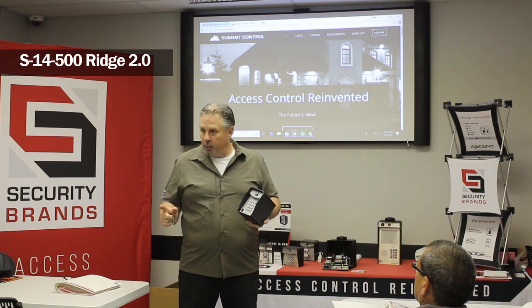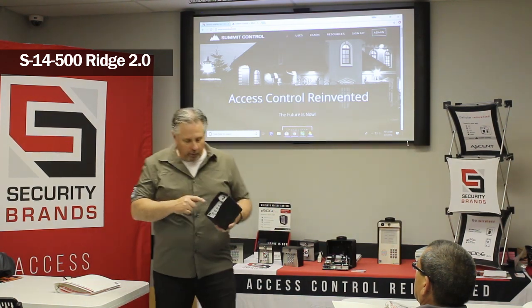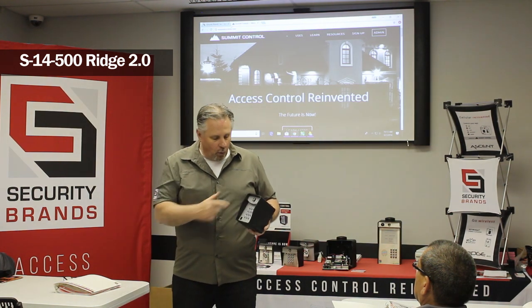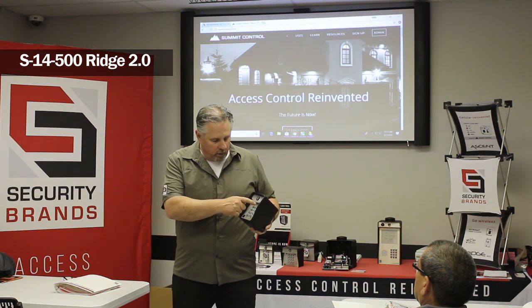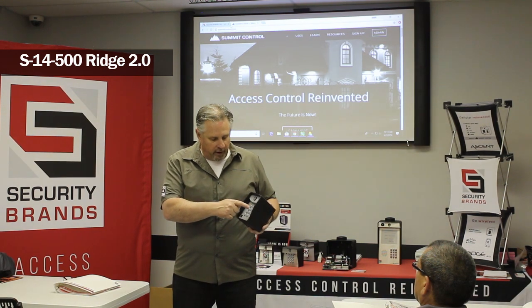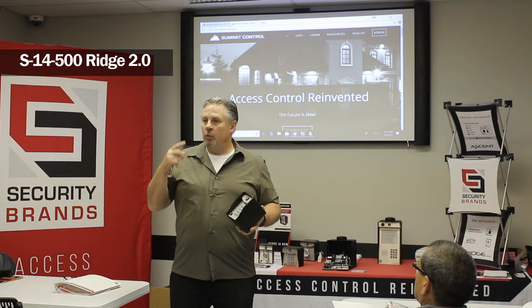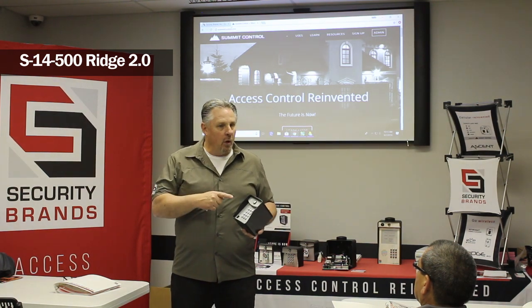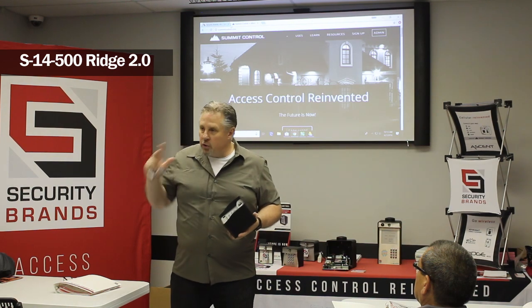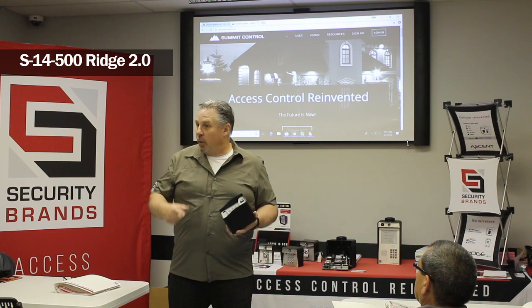1251 takes you into the programming mode. Same process for programming all my keypads. 1 to add codes, and we'll add 3214, and we'll add 1236. I just added 2 codes. Pound to exit. So 4 steps. Master code is 1251. You can change that to something unique for the homeowner. The homeowner can change it.